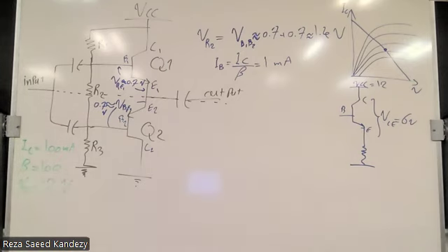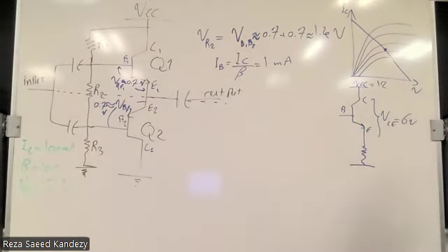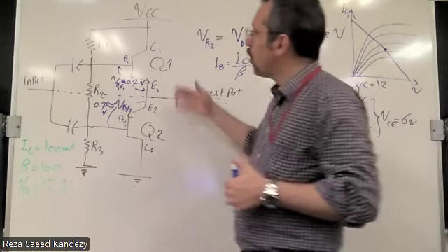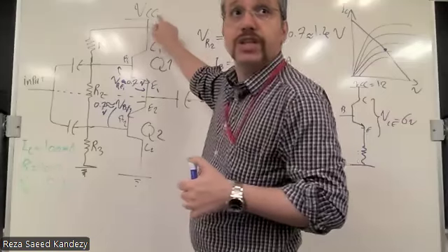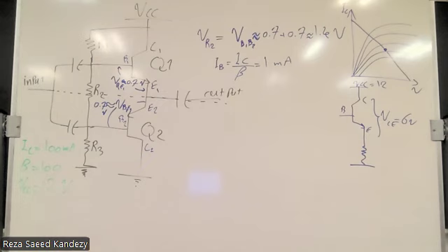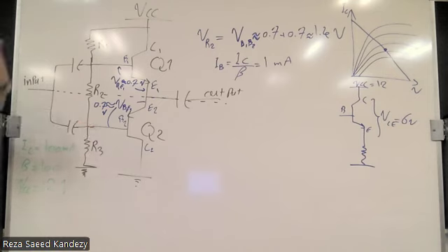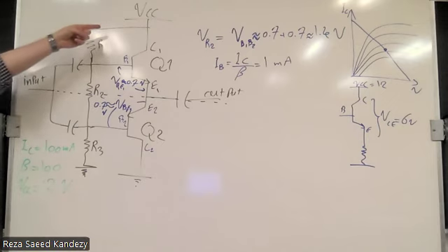Now, when we talked about strong biasing, we know we supply the power of our system by VCC, which is a DC source, and our signal is going to be an AC. What does that mean? That means whatever voltage we have here, which is the voltage of the bases, would experience a certain transient with an offset of the DC. Are we good?